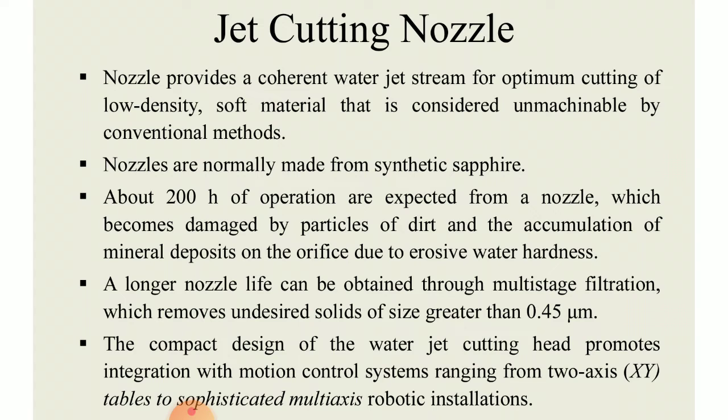To maintain the diameter from 0.1 to 0.3 mm, the nozzle will play a vital role, and generally the nozzle will also get eroded from the high pressure of water or fluid coming out of it. So generally its use is restricted to around 200 hours of operation.